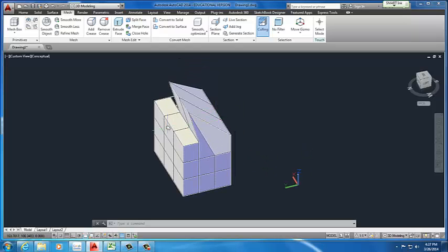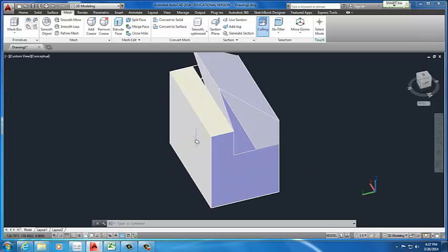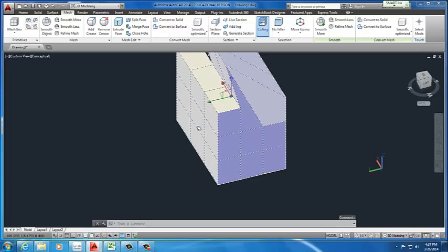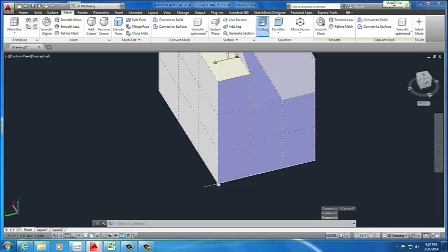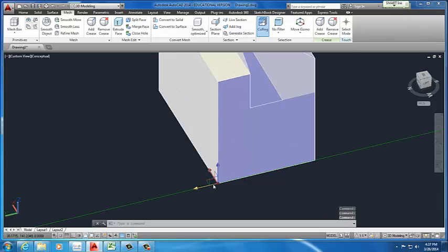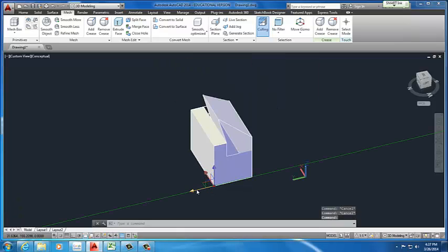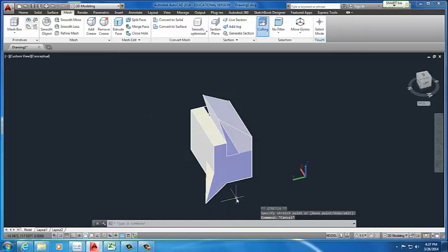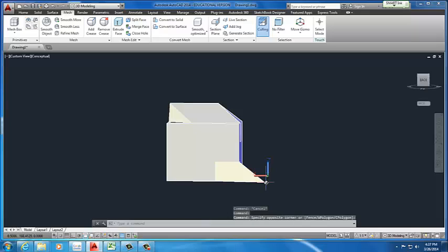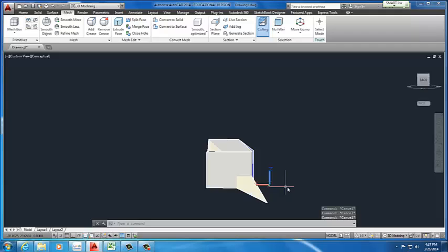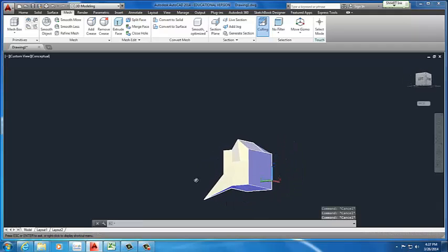Not only can you flex lines like this, you can also select points at corners. So when you select the corner, like so, you hold control and you select that corner, you can also drag it out. Something like this. If you want to even go lower, you can again click on the corner, holding control, and you go Z. So you have something like this, a pointing corner.